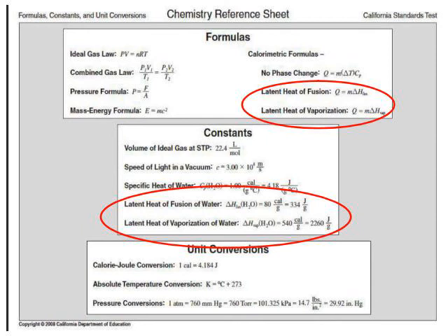The formulas are here on the back of the periodic table: latent heat of fusion and latent heat of vaporization. Essentially, they have the formula Q equals mass times the heat of fusion, or Q equals mass times the heat of vaporization. Notice there's no temperature change at this point. If we were to do a delta T on this diagram, that flat part has no temperature change, so it would equal 0. So we have to use a slightly different calculation.